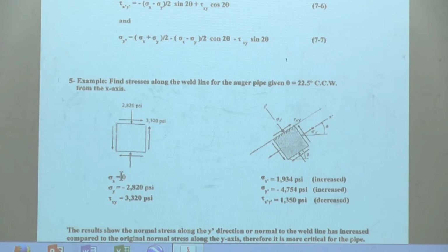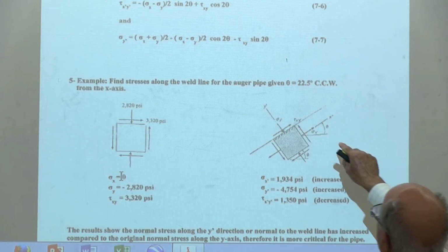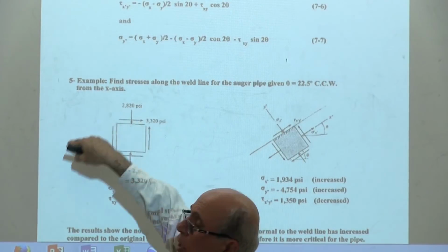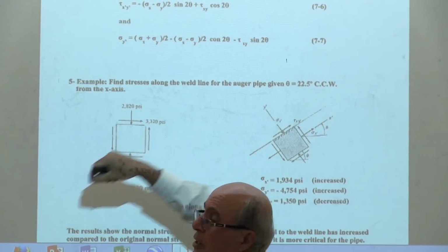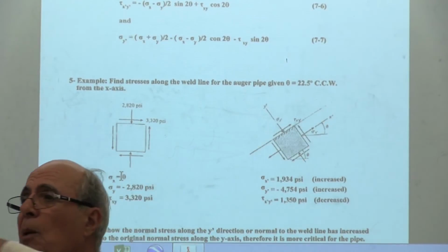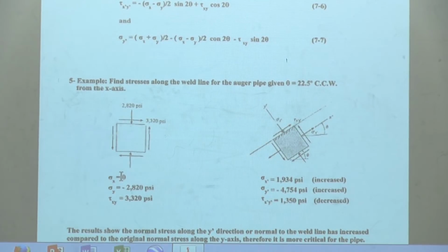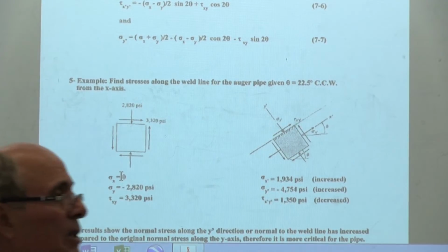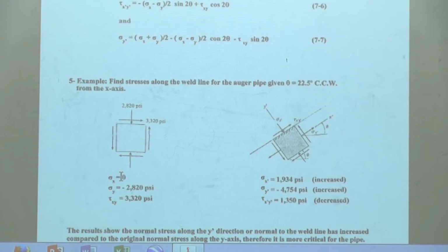So all the stresses from 0 degree, which is this one, theta equal to 0 degree, to 180 degree, which is back again to the normal, all of them become on the circumference of a circle. That circle shows you everything. Is that correct or not? And it shows you the maximum stresses. It shows you the principal stresses, which we call principal stress, the maximum shear, etc., etc. Yes or no? Correct? Let's do that for an example.